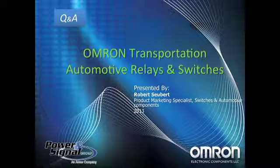Our next question: if smaller auto relay switches the same current, why use one with larger footprint? Well, it depends on the customer's layout of his board. Most people basically are trying to save space, but there's a lot of older generations of relays that still have the same footprint. So I'm assuming what the customer is asking, there is an advantage to go to smaller, but if current designs are using a larger one, then stick with the larger one.